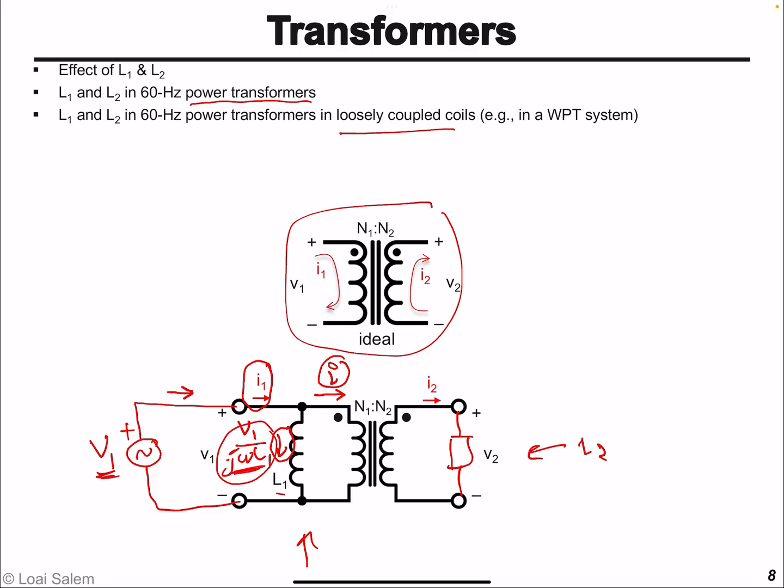So in order to avoid this extra current that's flowing in the self-inductance of L1 or self-inductance of L2, if we represent that self-inductance by L2 in the secondary side, in order to avoid this extra current in the source or increasing the current in the source driving the transmitter, what we do, we add a capacitance C1 in order to cancel the self-inductance L1 on the primary side. And I'll get to this point later on in detail in a following video. But all I want you to know right now, the self-inductance of the transmitting and receiving coils in a wireless power transfer system is small in value, which causes basically loading on the source driving the wireless power transfer system. And so we need to add a series capacitance to tune out this inductance and avoid this extra current in the source.